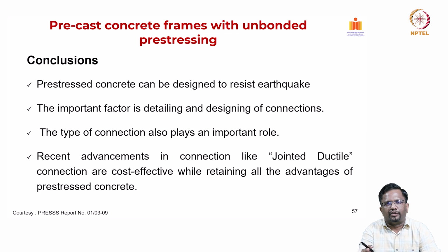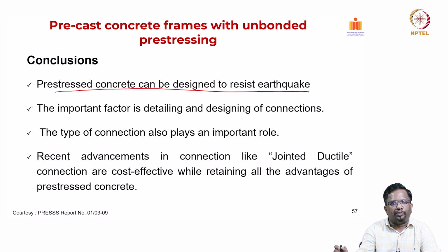The idea of this particular chapter was to give you an overview of different connections and how seismic designs are done. We can say pre-stressed concrete or precast elements can be designed to resist earthquake forces. The important factor is detailing. The detailing is most important. The connections have to be detailed well, and the design of connections has to be done in a careful way.